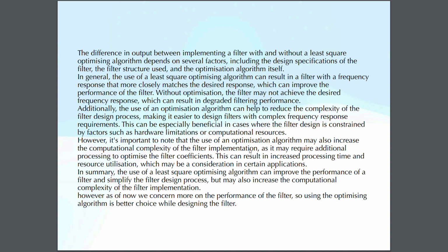So though we are getting a good frequency response from that optimized filter, the drawback here is that we are doing more computation, so the computations which we are doing become complex. And also, because of the computational complexity, the processing time to optimize the filter coefficients will also increase.